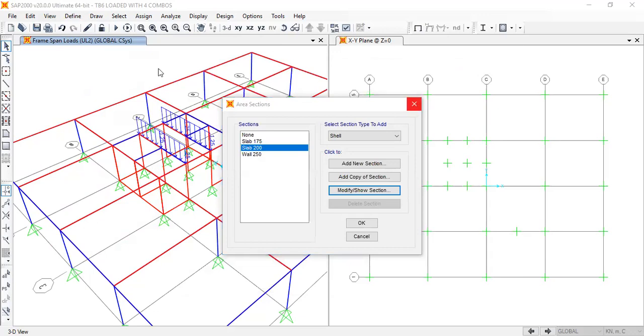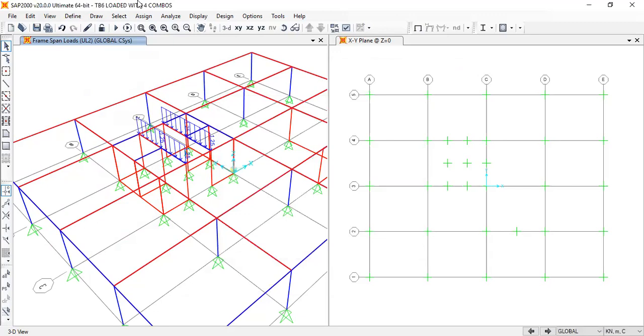No, secondary beams, you have to be careful, because you need to keep it as simply supported here. That is more advantageous, because if you have something connected to this, when this beam deforms, when this beam gets a moment, it will apply a torsion to these end beams, right.